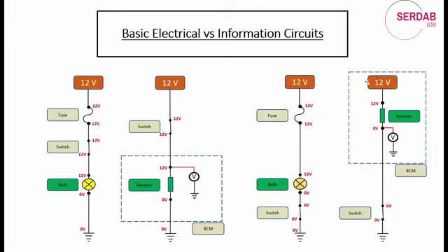This time, inside the module, we have the load here, which is just a resistor. And this resistor can be a high resistance, which would allow very low current and very small wires to be used by the module. So we don't need to waste any power. We just need a way to monitor that the voltage changed. So this resistor value could be 1,000 ohms, it could be 2,000 ohms, 10,000 ohms. They can choose whatever value they want within certain limitations, but they're only trying to make a circuit using this resistor as the load so that they can monitor the change in voltage inside that circuit.